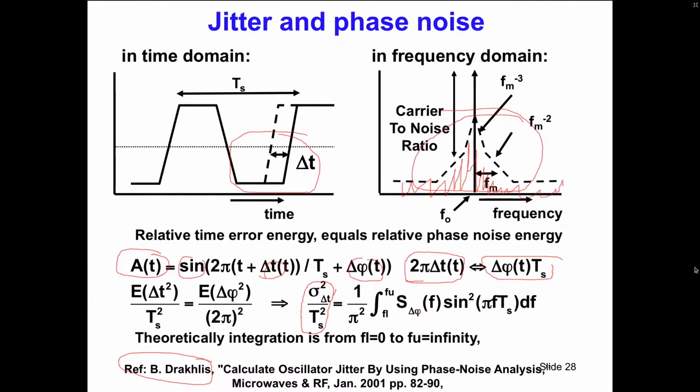Well, obviously you can translate from here to there, but it is not possible to go from there to here, because if you have 1.4 picosecond jitter, you do not have sufficient information to subdivide the phase noise in these different regions. So keep in mind, phase noise and jitter are basically representations of a similar phenomenon. From phase noise, you can always get the jitter, but not the other way around.